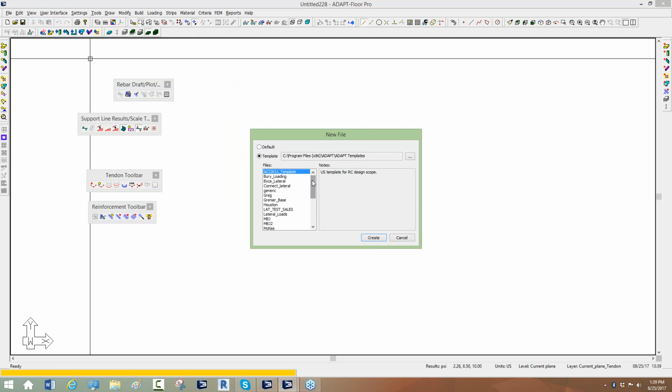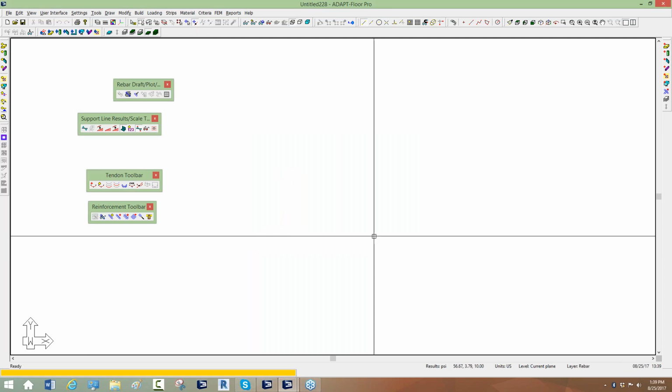So if I had written 100 combinations in that previous template, and then I come here and use the webinar template, then the file and the load combinations are there for me to use. The important thing to remember is those combinations have load cases assigned to them: seismic, wind, gravity. So you have to follow the same naming scheme for wind and seismic.